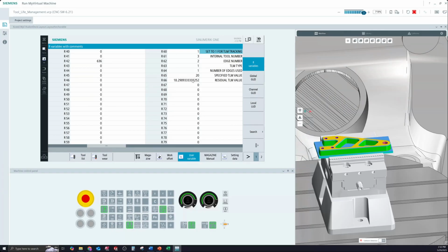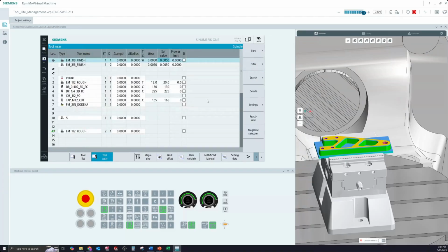I think this is huge, especially in grinders, because you could use this for the wheel. And really the wear that we just talked about, wear in grinders probably comes a little bit more into play because you are starting to wear that wheel quite a lot. So you might want to check either time or wear, and actually have that as it starts to degrade the wheel. So I think that is definitely a good one.